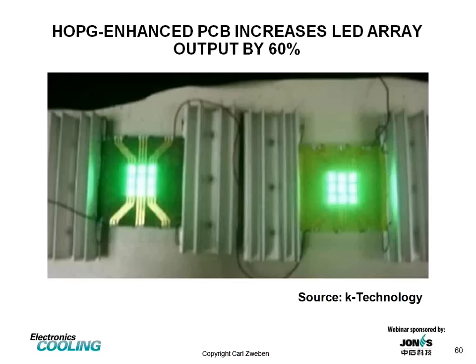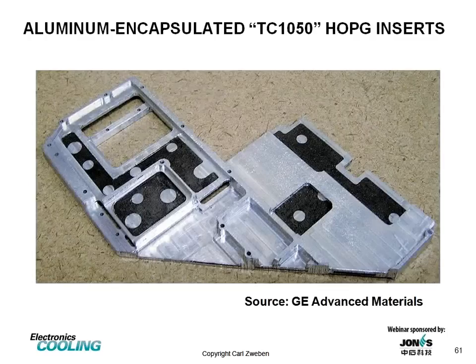As I mentioned, heat dissipation is a major problem in LEDs, light-emitting diodes, and here we have an application where highly oriented pyrolytic graphite is attached to the printed circuit board to dissipate heat, and doing so increases the efficiency of the LEDs and increases output by a staggering 60%. So it clearly illustrates the importance of thermal management in some photonic applications.